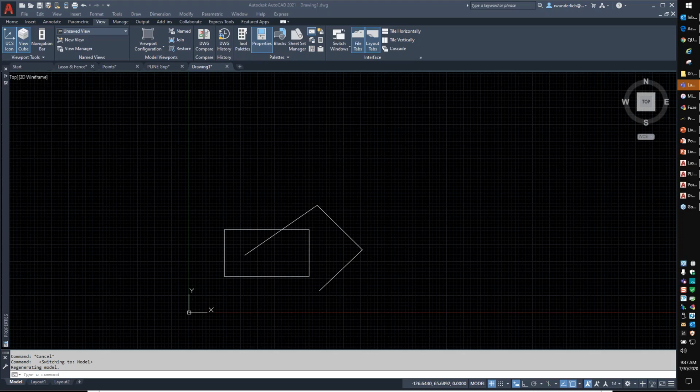Can you briefly discuss the student version of AutoCAD and the watermark that is permanently associated to those DWG files? Yes, I can. The student watermark has never actually been removed from any of the AutoCAD versions that had it. They briefly turned off the EDU stamp, which is the watermark you're talking about. In order to remove it, there are a couple of utilities out there that can help you identify what was created with it. There are also other ways that sometimes allow you to get around it. You may have to DXF the file out to an R12 DXF, which will strip all of that information, reopen the DXF after you've closed and reopened AutoCAD, and then resave it as a DWG, and that should help get rid of that watermark in a lot of cases.